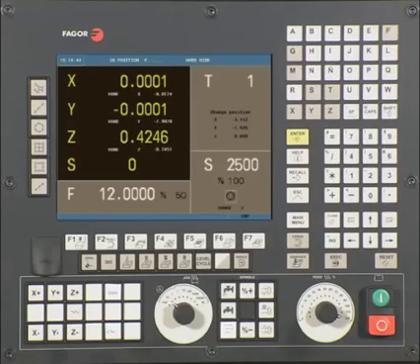When the execution of the bidirectional milling operation is complete, it will be necessary to calibrate the next operation's tools on the newly established part surface that was just machined. Tools 6, 7, and 2 will need to be calibrated at this time. Here is a quick review of the tool calibration process learned in previous steps.